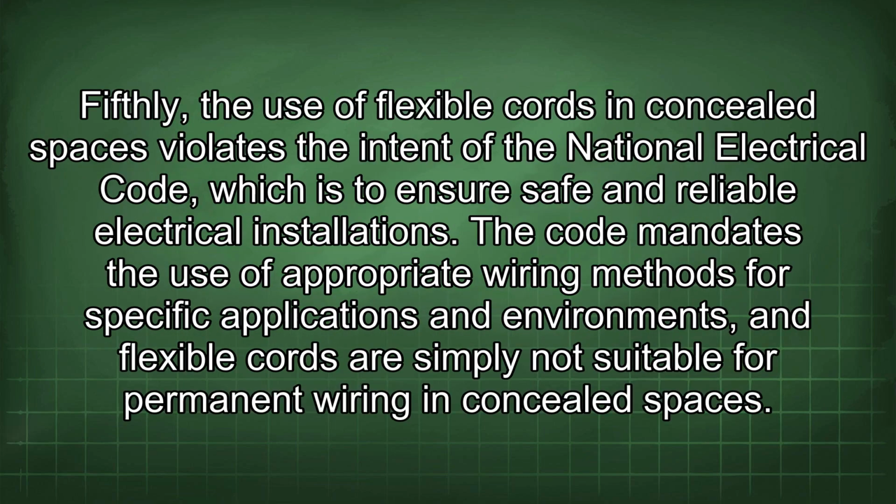Fifthly, the use of flexible cords in concealed spaces violates the intent of the National Electrical Code, which is to ensure safe and reliable electrical installations. The code mandates the use of appropriate wiring methods for specific applications and environments, and flexible cords are simply not suitable for permanent wiring in concealed spaces.